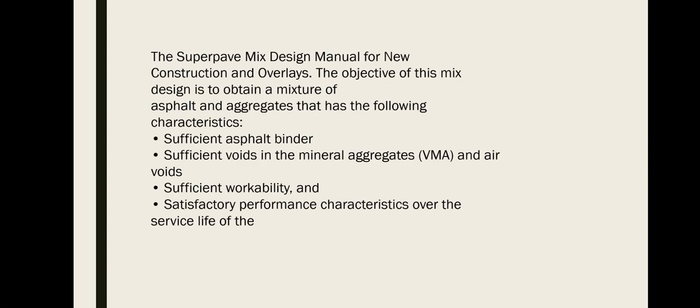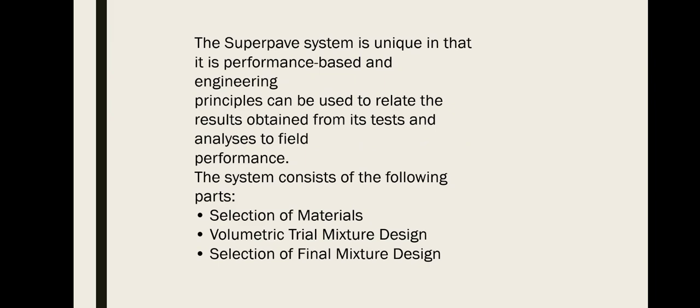The Superpave mix design manual is for new construction and overlays. The objective of this mix design is to obtain a mixture of asphalt and aggregates that has the following characteristics: first, sufficient asphalt binder; sufficient voids in the mineral aggregates, or VMA, and air voids; sufficient workability; and satisfactory characteristics over the service life. The Superpave system is unique in that it is performance-based engineering. Principles can be used to relate the results obtained from tests and analysis to field performance.